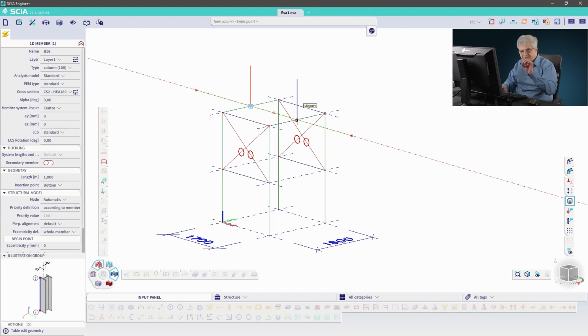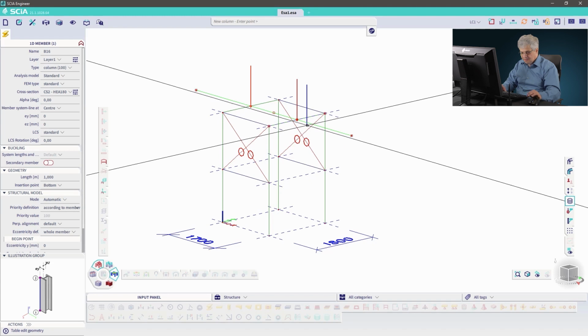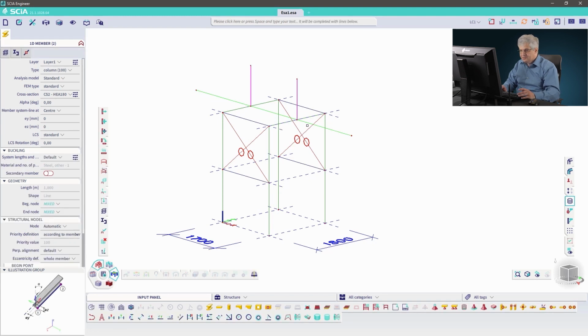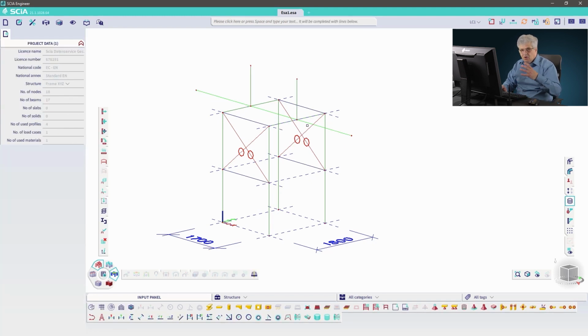You have to stay with your mouse for half a second on the point, or at the beginning you can put F7, this tracking, off, then it's a little bit quicker, and escape. So I use the tracking for the trainings only if I need it, and then after them I put it off. Later you will use it as standard.